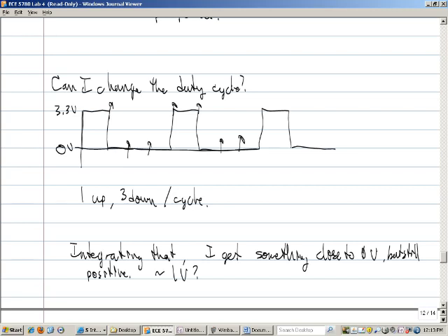Anyway, what you're going to do is take your voltage range over here from 0 up to 3.3. Different duty cycles will correspond to different DC average values in between these levels. And what you're going to have to do is churn out different duty cycle waves, send it through your integrator circuit, and see what values of DC you're getting. And then also for different duty cycle waves, send that through your function generator's VCF input and see how much of an impact it has on frequency.